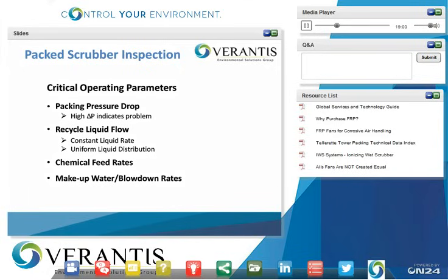Recycled liquid flow needs to be at a constant rate. It should always be at or slightly above the specified design rate to make sure that we have the proper liquid to gas ratios. Uniform liquid distribution is very, very important, because non-uniform liquid distribution can result in dry areas in the packed bed, or possibly areas where you just have low liquid to gas ratio. So then again, the liquid and gas aren't in contact as optimally as possible, and that can reduce scrubbing performance.